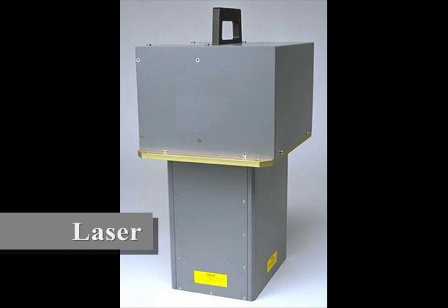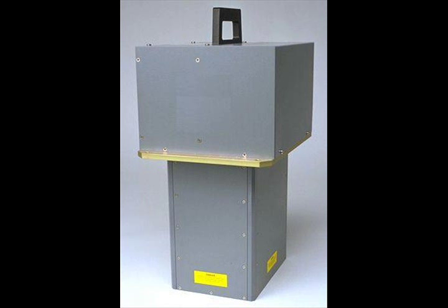The laser is the primary sensor in the Lidar system. The laser is used to record the distance to a target. This is accomplished by emitting pulses of laser light. The pulses travel down from the platform, reflect off the target, and the energy is returned to the collector. The laser can fire thousands of pulses per second.